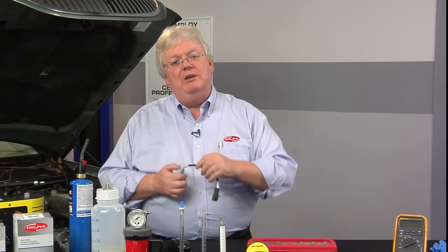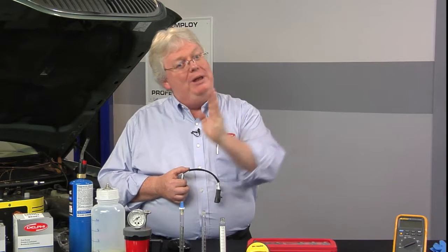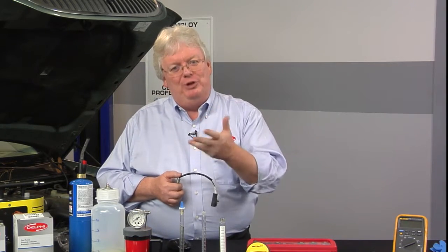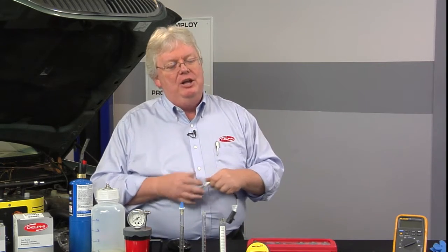So that's how you can see it if you don't see a PID for rear fuel trim, as many aftermarket or even OE level, but not true factory, scan tools do not show rear fuel trim as a PID. Something to keep in mind when you're doing diagnostics. Look at that total fuel trim, because total fuel trim is what a tech needs to go by in diagnostics, because it's what the PCM goes by in diagnosing whether we have a rich or lean condition worthy of turning the light on.